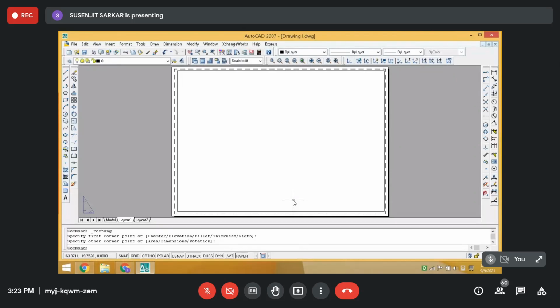But once you have set your page to A4, by default it will take 297,210. But here you have some hidden lines, so you cannot get any coordinate beyond this, or any line printed beyond the hidden line. Now, if you check this, move the cursor and you will see the coordinate. This is 15 in x.